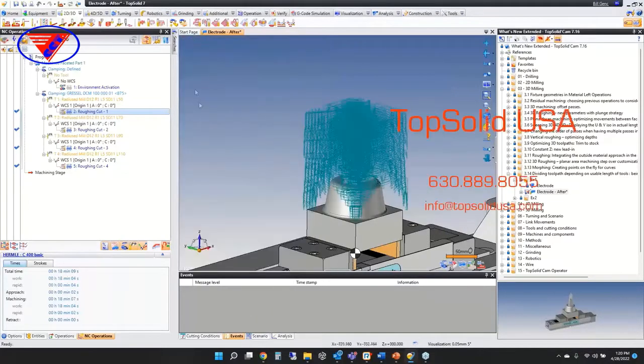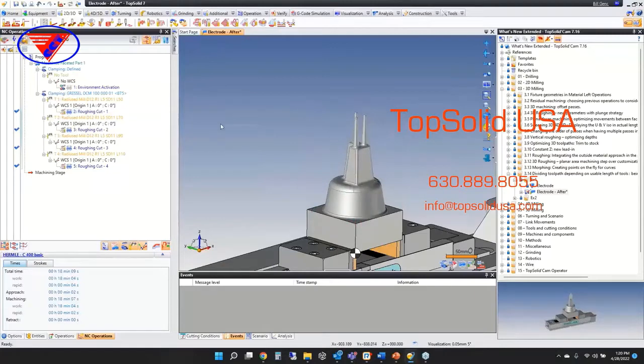And then what happens when you click OK is it took that original roughing toolpath and it now divides it up based on what each of those tools can actually reach without colliding. So the first tool is machining there, the second tool is machining there, the third tool is machining all of that, and the fourth tool is machining all of that. So you have the ability to optimize your toolpaths. I don't believe it's limited to just roughing. I think you can use it on all the 3D finishings as well.